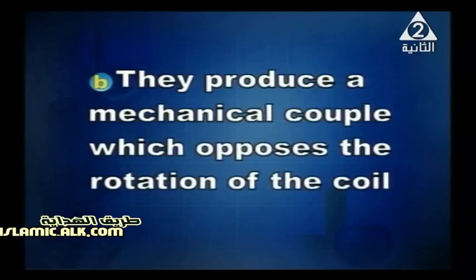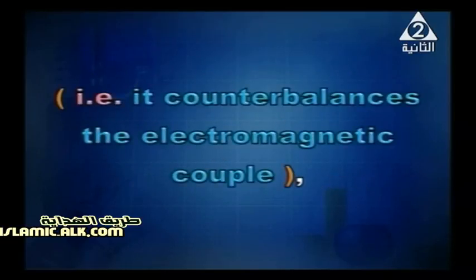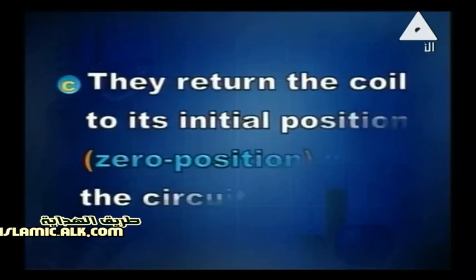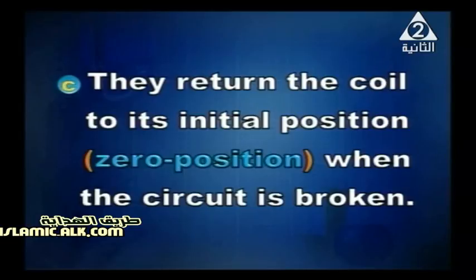They produce a mechanical couple which opposes the rotation of the coil, which counterbalances the electromagnetic couple. Also, hair springs return the coil to its initial position, to 0 position, when the circuit is broken.